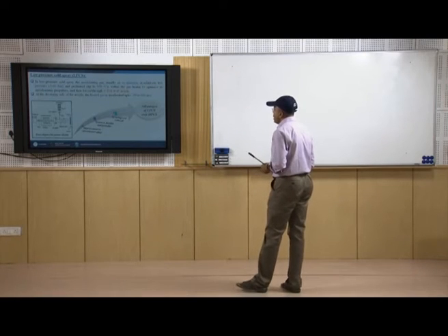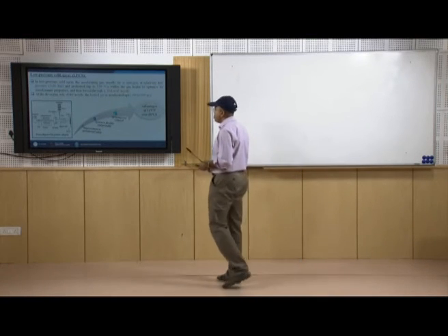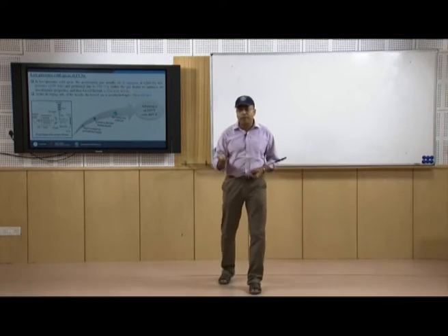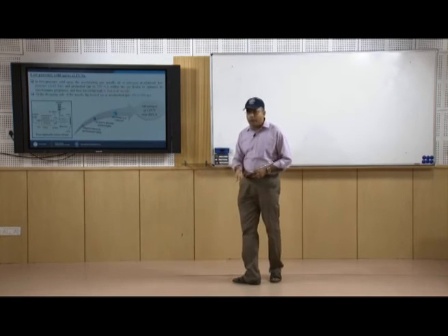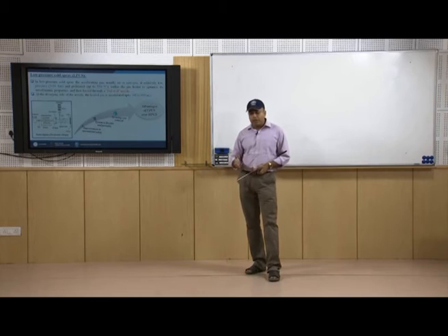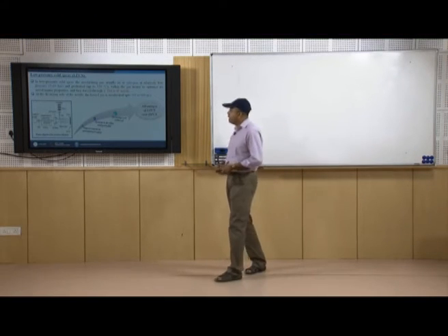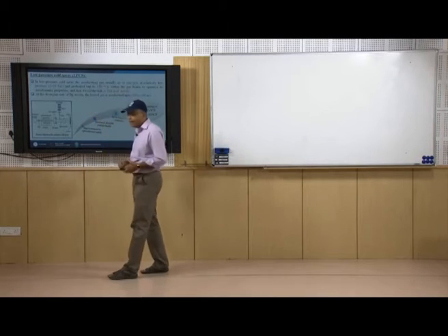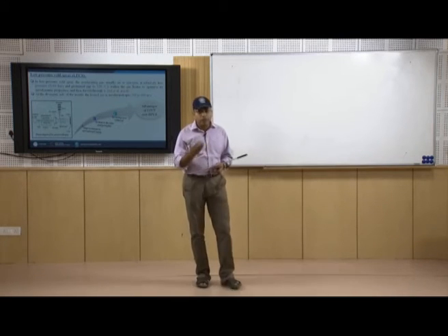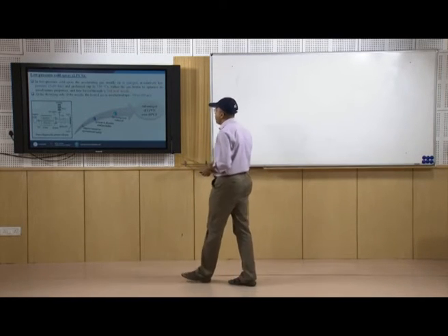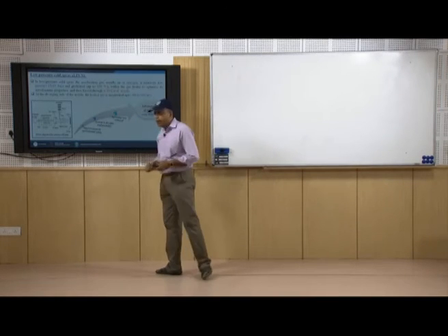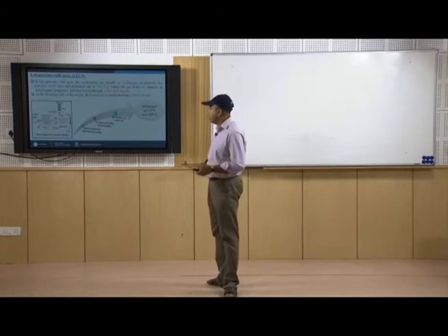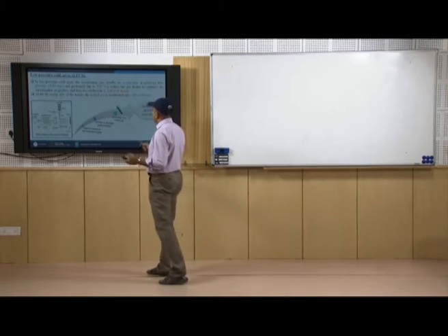Next, we are going to discuss the low pressure cold spray. In the low pressure cold spray, from the name itself we can understand that here we are using very low pressure compared to the high pressure. If you remember, for the high pressure we applied a pressure of 25 to 30 bar, but in this particular case we are applying a pressure of 5 to 10 bar only. At that time we used preheated gas up to 1000 degrees centigrade, but in this case we are preheating the gas up to 550 degrees centigrade. So in the low pressure case we are reducing the gas temperature as well as the pressure of that gas. Otherwise everything is the same.